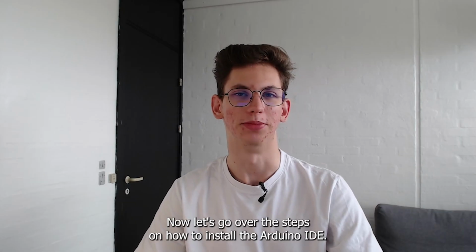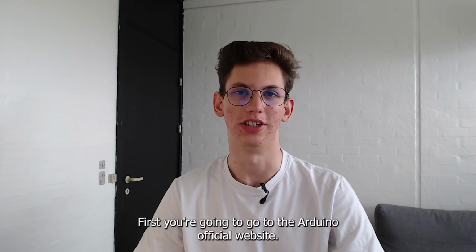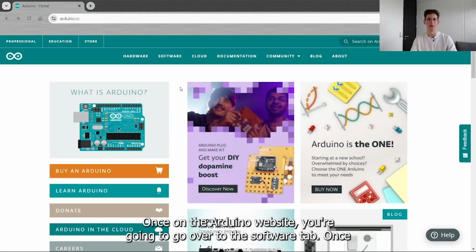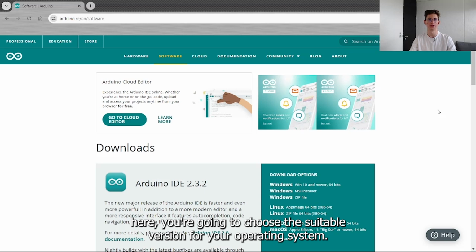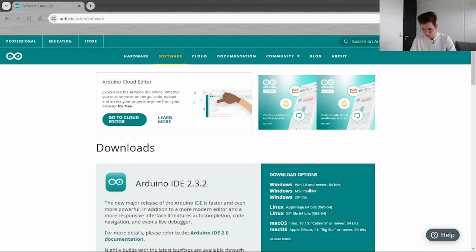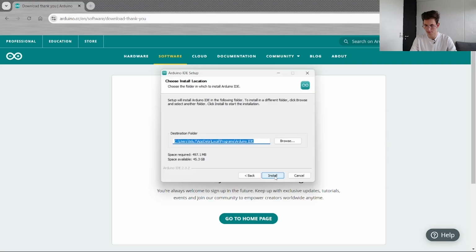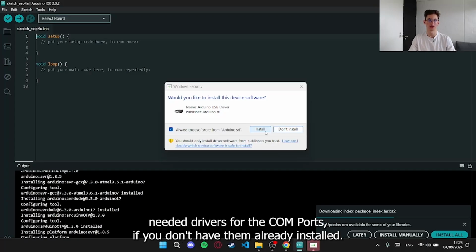Now let's go over the steps on how to install the Arduino IDE. First, you're going to go to the Arduino official website. Once on the Arduino website, you're going to go over to the software tab. Once here, you're going to choose the suitable version for your operating system. Remember to also install the needed drivers for the COM ports if you don't have them already installed.